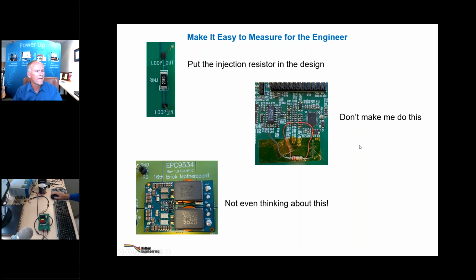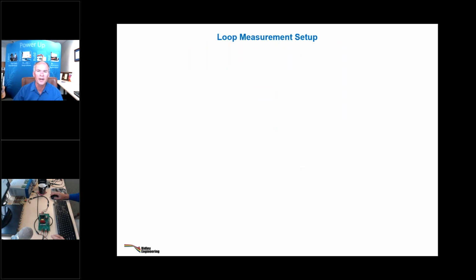What's a good rule of thumb when hooking up to grounds? Right, pay attention to grounds. It's like I say, it's experience. If you're measuring 60, 70 dB loop gains, you've got to have things grounded properly. And that doesn't mean necessarily everything grounded. You've just got to judiciously ground things to get the results that you need from the system. But it's practice. There's no rule that tells everybody ground this, don't ground that. Every system is different. But if you don't measure, you're never going to learn.